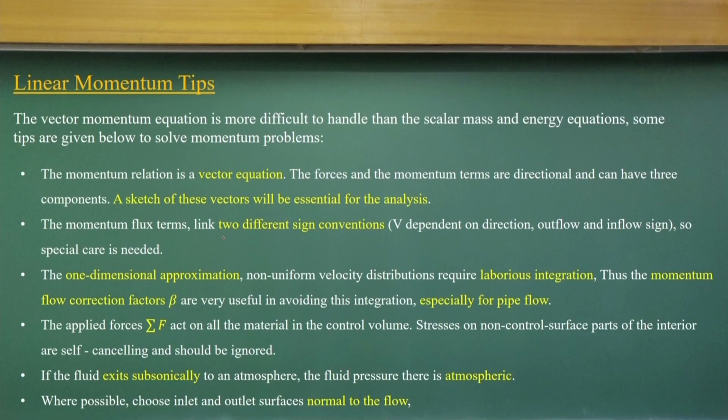So, when you solve any linear momentum equation, please sketch the vector components. Then visualize the fluid flow problem and solve it, because it is a vector equation, so try to apply it as a vector equation. Second, we always compute the momentum flux terms, influx and outflux, in their directions.